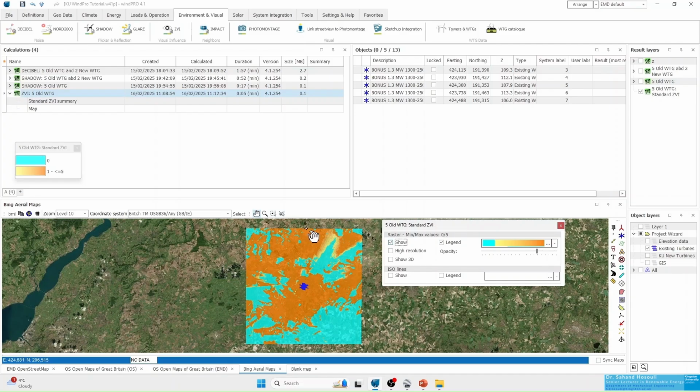One point that you need to remember here is that it's a bare earth model, as we mentioned before, so it considers only the terrain and not any obstacles like buildings, streets, etc. The other point to mention is that when it says 5 wind turbines are visible, it tells you how many and not how much of those turbines are visible. It might be only a little bit of the tip of the wind turbine that would be visible from this distance if we don't consider any obstacles.